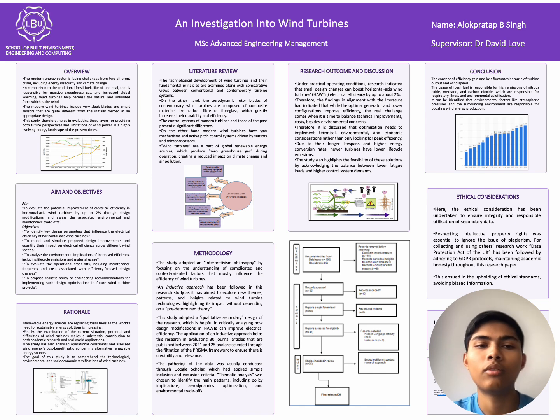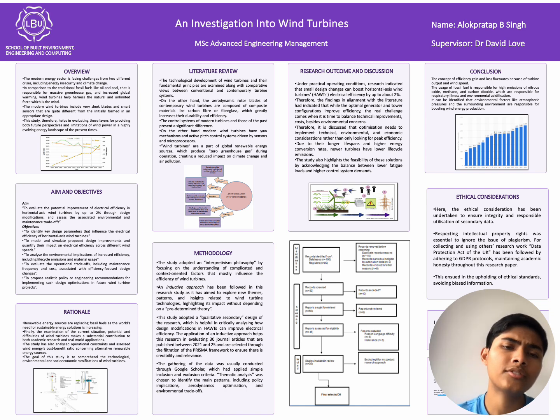The technological development of wind turbines and the fundamental principles are examined along with comparative views between conventional and contemporary turbine systems. The transformation of wind energy from kinetic to mechanical and finally electrical energy forms is still the fundamental idea behind the operation of wind turbines, both modern and traditional. The wind drives the rotor blades of contemporary horizontal axis wind turbines, which in turn drive the shaft that is connected to the generator through the gearbox. The aerodynamic rotor blades of contemporary wind turbines are composed of composite materials like carbon fiber or fiberglass, which greatly increases their durability and efficiency.